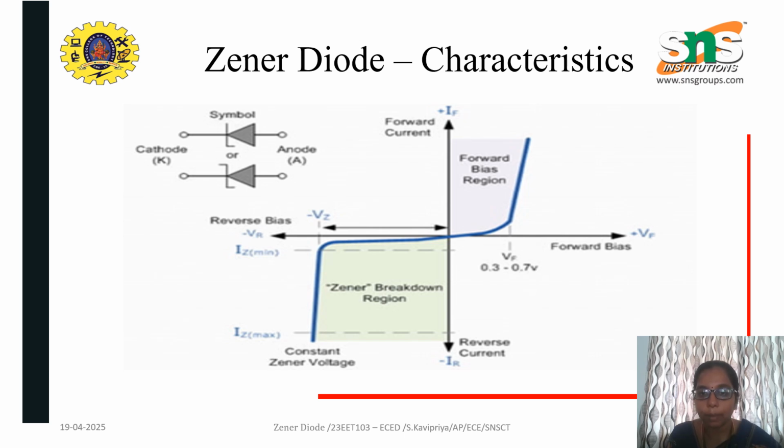In the case of forward bias condition, there will be a gradual increase in the current as the voltage is increased up to a threshold value. The threshold value ranges between 0.3 to 0.7 volts. Once the threshold value is reached, the barrier between the P and N type material completely vanishes. It results in a recombination of holes and electrons. More electron and hole pairs will be created, which results in a rapid increase in the flow of current.